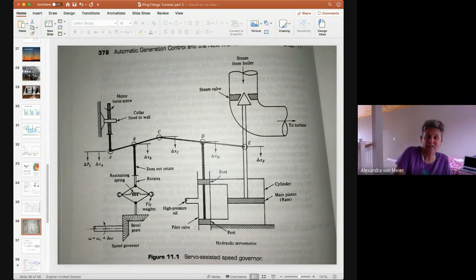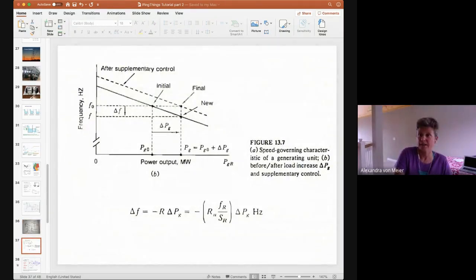Now, that control system is not exactly easily compatible with advanced inverter controls. So that's a whole other subject. I mean, inverter controls, which are power electronics, and you can tell them to do anything you want them to do, and they will do it exactly, and they will do it quickly. But be careful what you ask for, because whatever the control schema is that you implement with your inverters may not play well with these legacy control systems. And that's a whole field of interesting research.